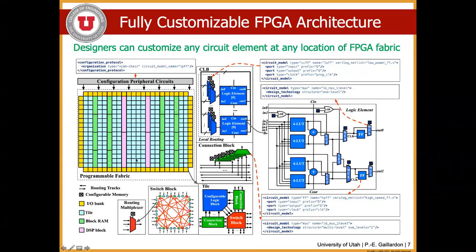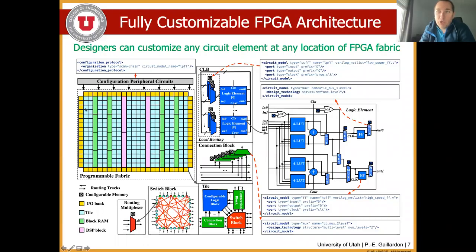Instead of describing this structure, one could imagine having just blocks of the same size. And instead of going through the full details of how your blocks are implemented, you can just say, hey, this block is a processing element with a .v file that you provide yourself, and you just let VTR handle the routing between them. And that is perfectly doable, and supported right now by the tool. Technology mapping would be a little bit harder. It all depends on your use case. What do you map into your CGRA? Are they ISA based or stuff like that?